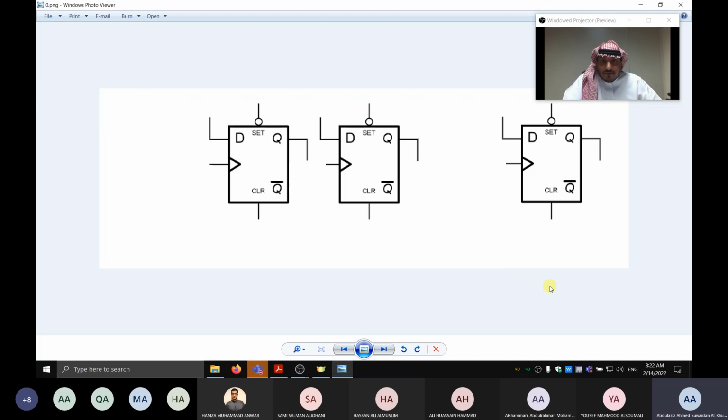So the second step, we separate the bits. Assuming you have multiple bits like 16 bits or 8 bits, you divide the bits across the flip-flops. Like that's the first bit, it's going to the first D flip-flop. The second bit is going to the second flip-flop. And so on to the last bit, which is going to the last flip-flop. Same thing for reading the memory. When you read what's saved on the memory, you read the outputs from the D flip-flops. You see, that's the first bit, the second bit, and then the last bit. You just divide each one to each D flip-flop.